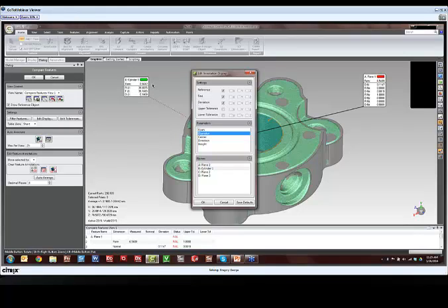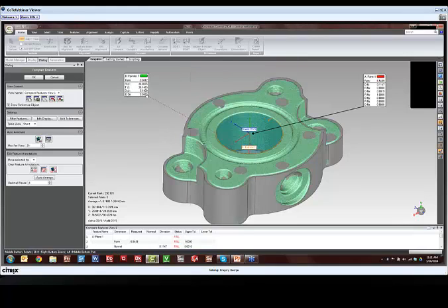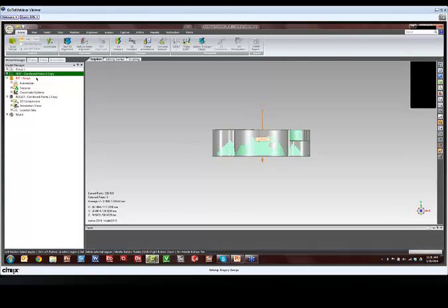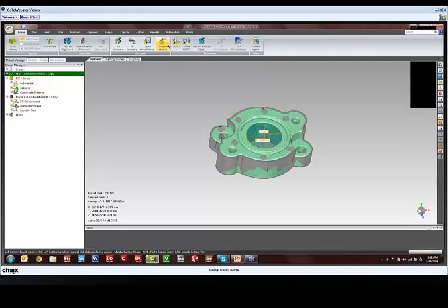You see, that's what I'm showing. If I want to add the direction of deviation as well, I can just add the 3D direction deviation and hit OK, and that'll update my annotation. And then just like before, I'm going to save that view in order to create a report later. So if I hit apply, we went ahead and created some compare features.